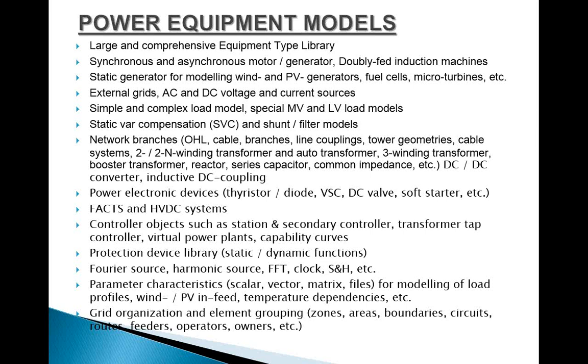Power electronic devices consist of thyristor, diode, VSC, DC valve, soft starter, etc. We can design and simulate FACTS devices in this PowerFactory software, and also analyze HVDC systems based upon that. Control objects such as station and secondary controllers, transformer tap controller, and virtual power plant, if we want to create, we can just create it.